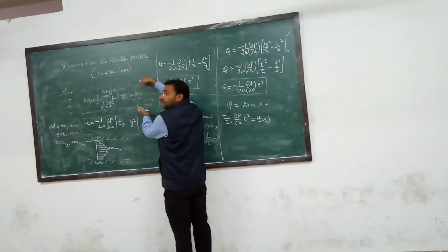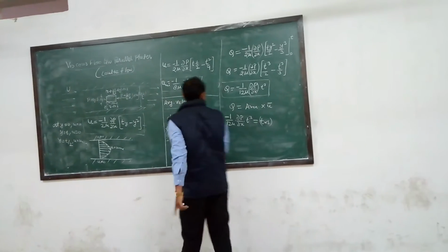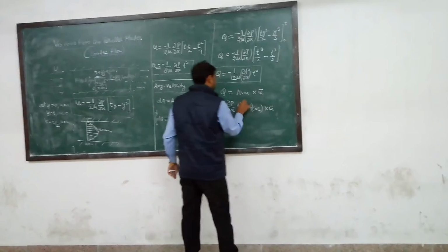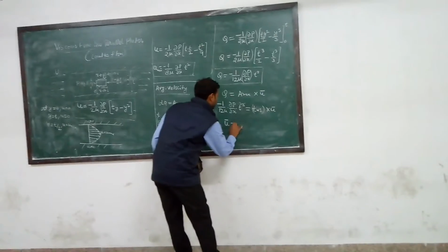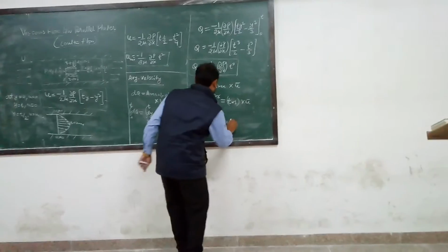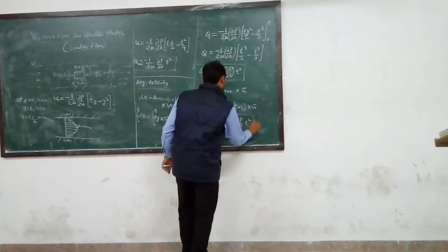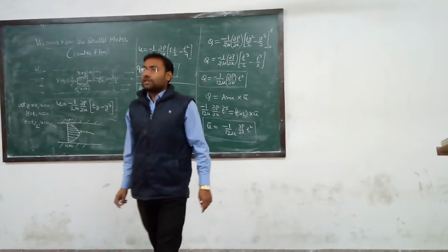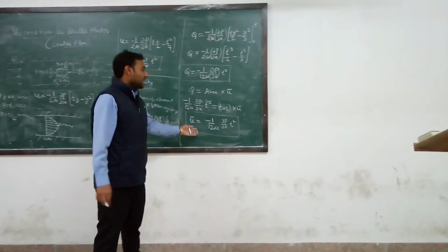The total area will be t multiplied by the depth, which is 1, multiplied by average velocity U bar. So t to t gets cancelled out, remaining is t². The U bar will be -1/(12μ) ∂p/∂x into t². This is the value of average velocity for the case of viscous flow between parallel plates.